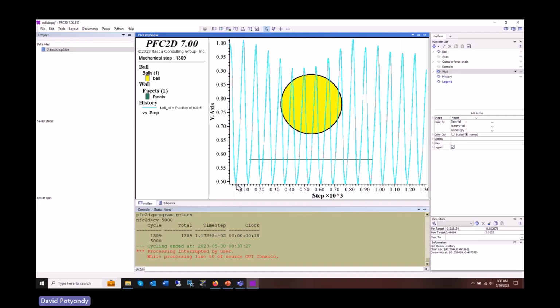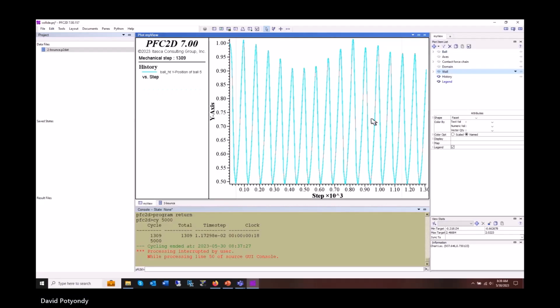And then the force is building up and it's pushing back. But look at the height. What is happening here? If there's no damping, just think you have potential energy in this system. You have potential energy at the top, mgh, and then when it gets to the very bottom and the velocity reaches 0, all the energy is stored as strain energy in the spring, which then causes it to start going up again. So if energy is conserved, it should always bounce back to the same height. It's not doing that. This is worrisome.